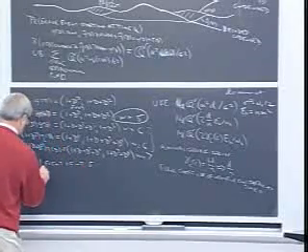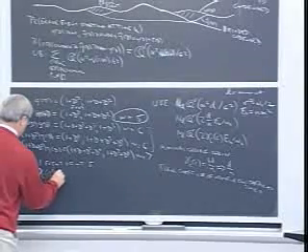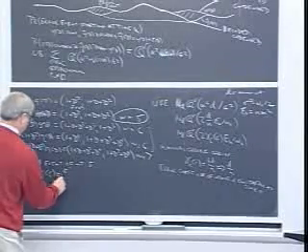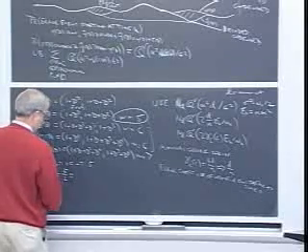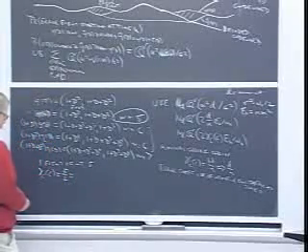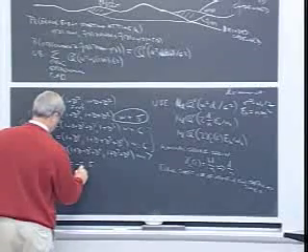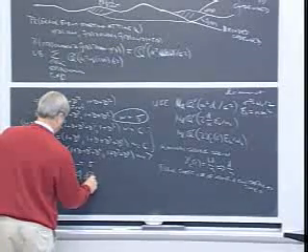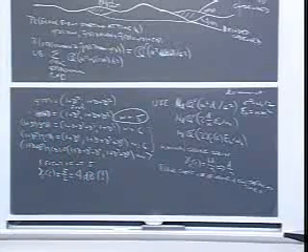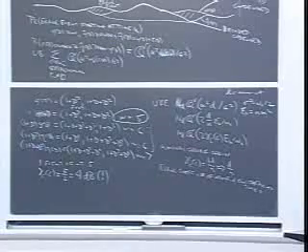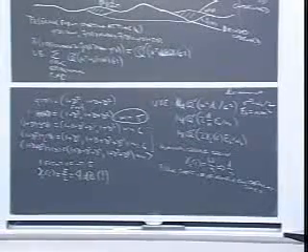So the nominal coding gain is 5 over n, which is 2, which is 5 is 7 dB, 2 is 3 dB. So this is 4 dB. That's pretty good. Nominal coding gain of 4 dB with only a 4-state code. Obviously a very simple decoder for this code.